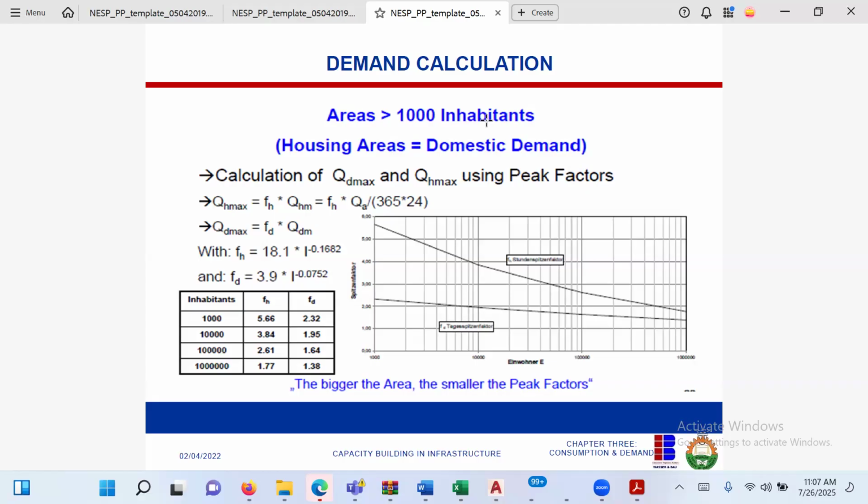So in 2025, you know that this city is going to grow to 10,000 in 20 years. They're going to use the parameters of 20 years to design today so that development will catch up with it. Please take note, this is very, very strategic and very, very important. Let it be one of your takeaways for today. You must forecast very well. And most times, what you use to build in that parameter is what we call the safety factor.